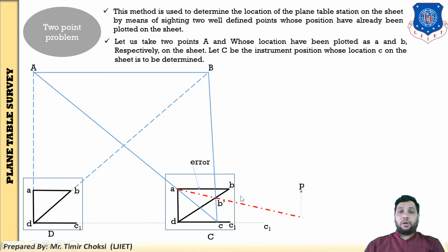Then rotate the plane table till the A line, B line and P line intersect in one line. Okay, I repeat this step. After putting the ranging rod, you keep the alidade touching at the AB line. Which line? AB line. Then, do not rotate the alidade, you rotate the plane table. Which instrument? Plane table. Clamp the screw, open the screw.